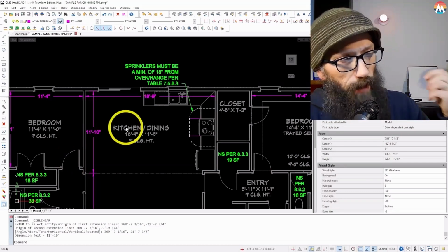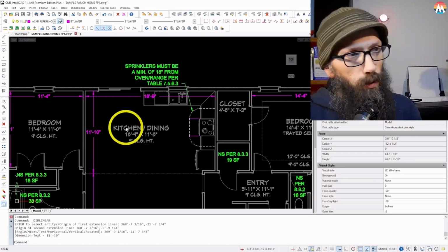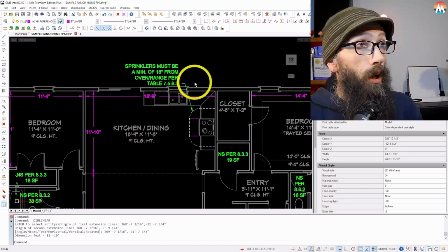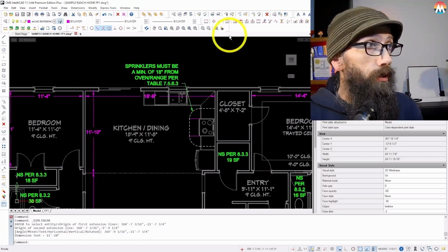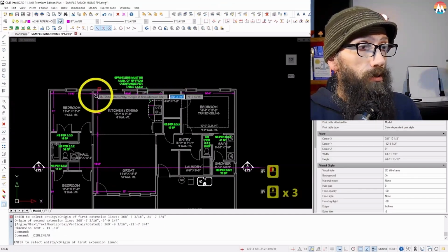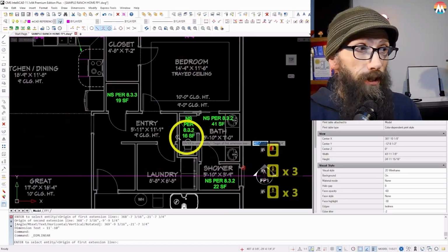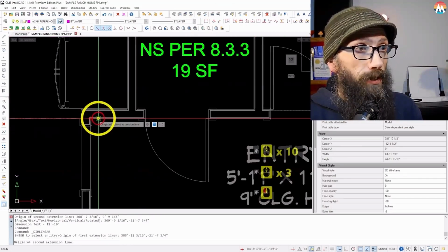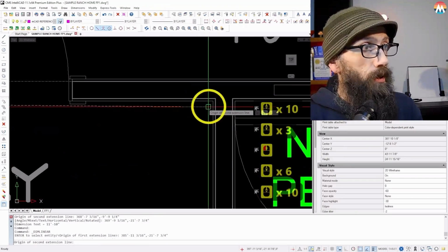It's roughly a 1/2 inch, and we're doing the calculations. We're going to use that number in the calc program. The important thing for what we're doing is that on that job order report, it said we are using that sprinkler at 16 by 16 foot spacing. And so that's 16 foot squares.